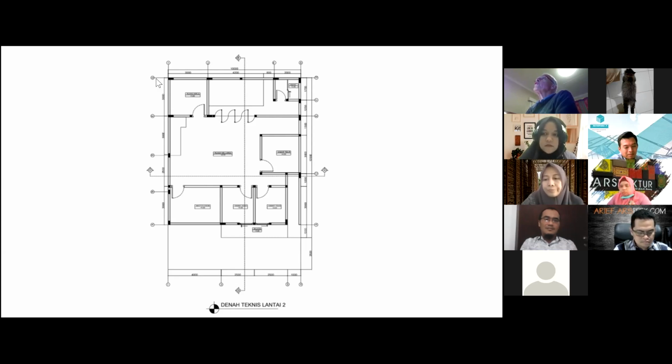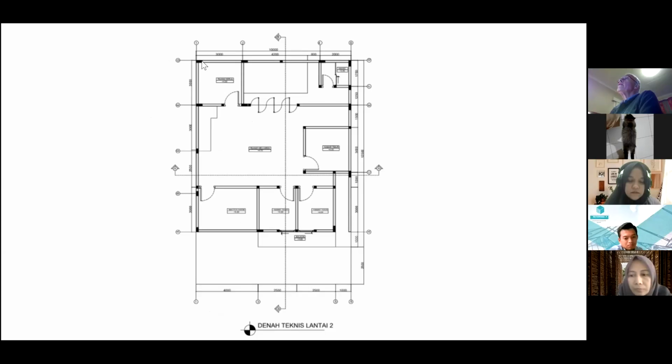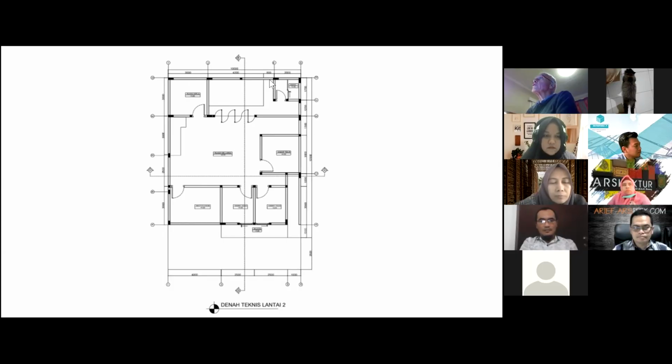And then we go to grid line G. And here we have excellent resistance in the X direction because this wall is solid right across. But we do have a problem because we've got this penetration here. The earthquake forces can't get into the wall over this length here. They're forced to get into the wall just at each end, here and here. And so that makes this wall not quite so effective.